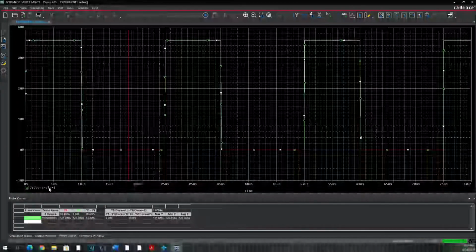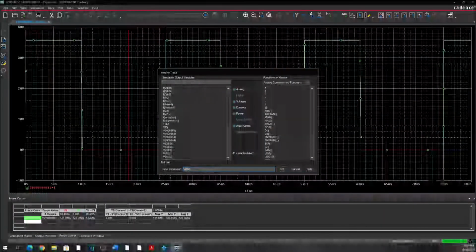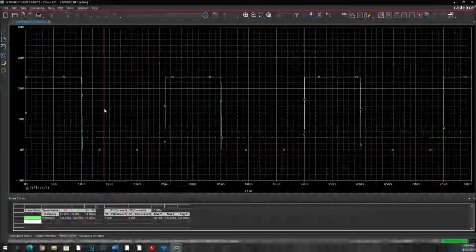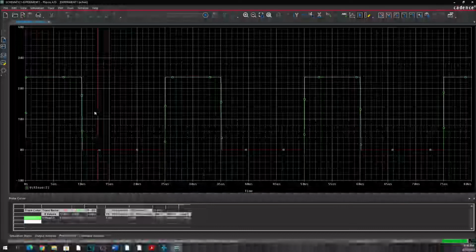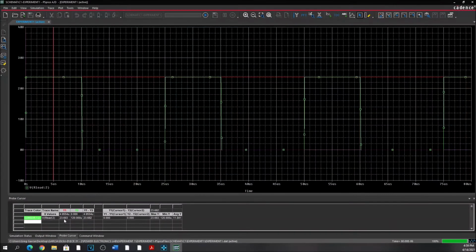Now, let's test the load resistor voltage. Let's go here, then modify the trace expression. V, our load, 2. Okay, now let's test the peak voltage value of our pulse in our load resistor voltage simulation. Now let's go to cursor, let's move here. We recorded a peak voltage value of 23.683 volts. So you can see it also rises for 1 nanosecond, then the peak voltage lasts also for 10 microseconds and falls for 1 nanosecond, then 0 volts for 15 microseconds. From there, it completes 1 cycle with a time of 25 microseconds.